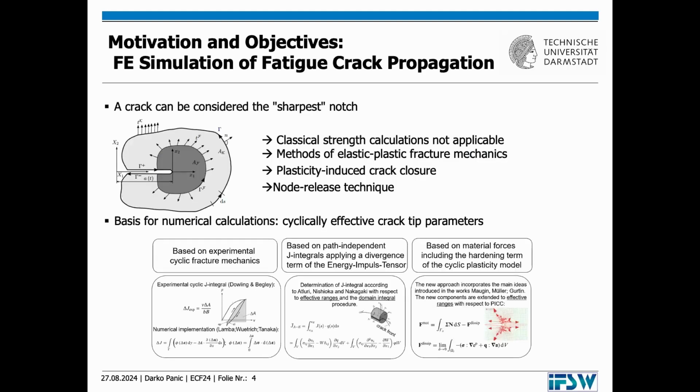To introduce you to the topic, as we all know, a crack can be considered as the sharpest notch. This sharpness makes classical strength calculation not applicable. Therefore, we use methods of elastic plastic fracture mechanics. So one key aspect we need to address is the plasticity-induced crack closure.